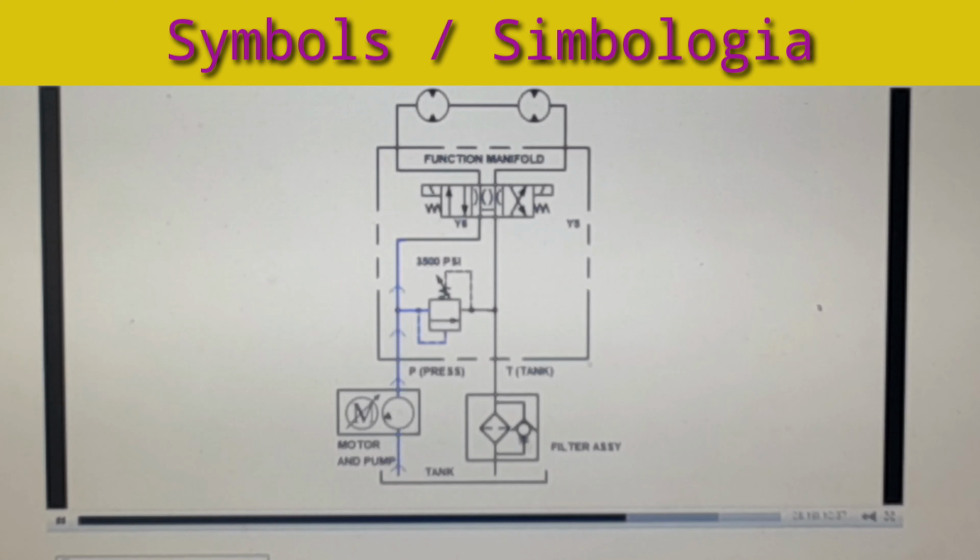In the first state of this example, the fluid travels through the hydraulic hose to the P-port of the manifold. If the 3-position, 4-way valve does not shift, the fluid cannot be directed to the drive motors, and it is returned to the reservoir. In the second state of this example, the 3-position 4-way valve shifts, directing the fluid to the drive motors. The drive motors rotate. The fluid exits the motors and returns through the tank port of the directional valve. The fluid returns to the reservoir through the filter.